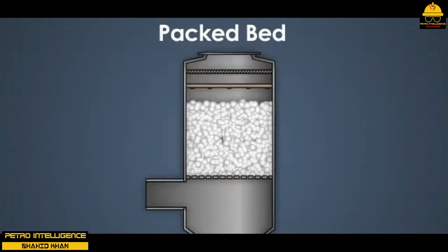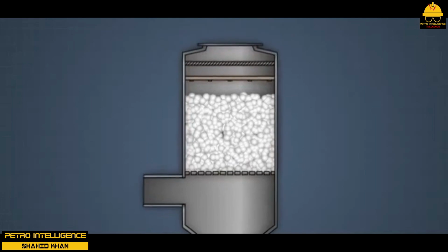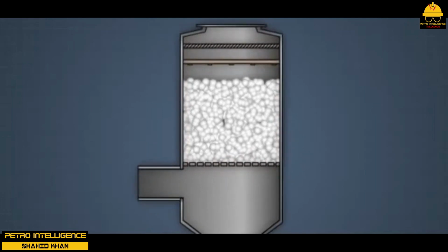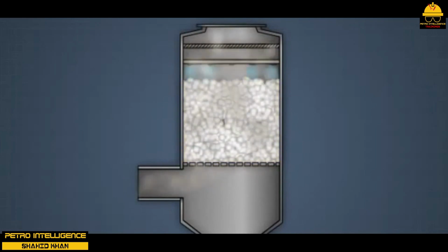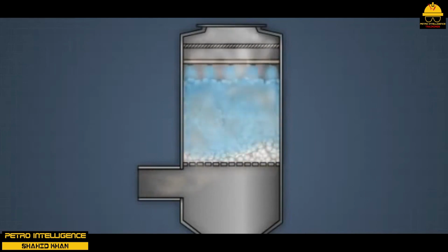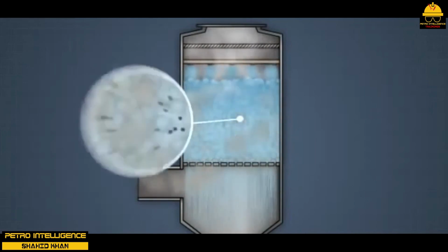Scrubber. A scrubber is a device used to remove chemicals and solids from process gases. Scrubbers are cylindrical and can be filled with packing material or left empty. As dirty gases enter the lower section of a scrubber, they begin to rise. As these dirty vapors rise, they encounter a liquid chemical wash that is being sprayed downward. As the vapors and liquid come into contact, the undesirable products entrained in the stream are removed.